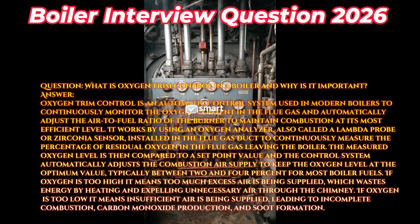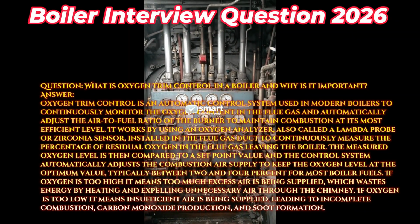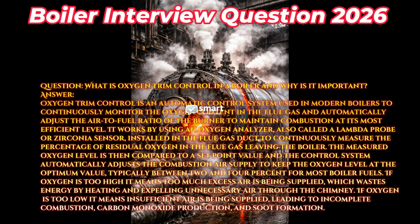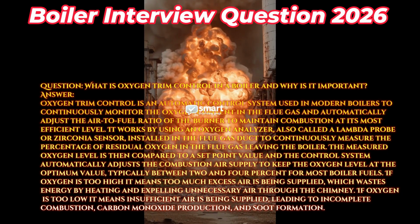If oxygen is too high, it means too much excess air is being supplied, which wastes energy by heating and expelling unnecessary air through the chimney. If oxygen is too low, it means insufficient air is being supplied, leading to incomplete combustion, carbon monoxide production, and soot formation.